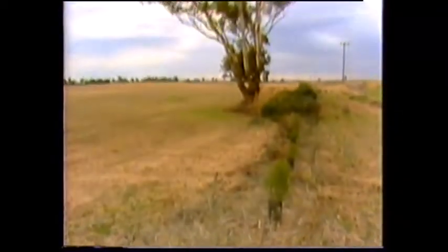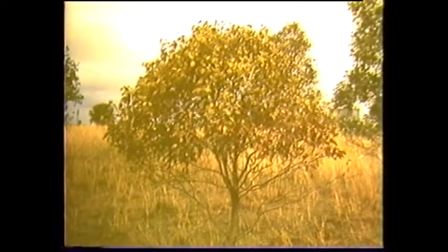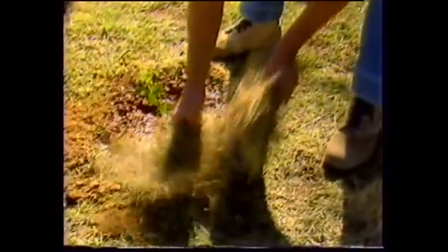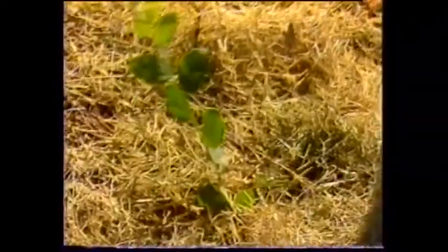Sandhills do present particular problems when it comes to establishing trees. Water and nutrients are easily leached through the soil profile, and as such, water stress often kills many seedlings. Another source of moisture loss is surface evaporation. Evaporation can be reduced by covering the soil around the plant with plastic, newspaper, hessian or mulch.